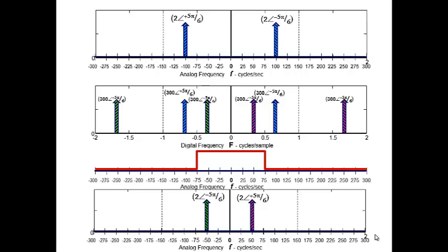What was that last time? Anybody remember? It flew up on the board real quickly at the end of the day on Monday, probably as we were dashing out. We take our original frequency and subtract off an integer multiple of the sampling rate, where this k has to be an integer, and it's got to be big enough so that this alias frequency is in the principal range.